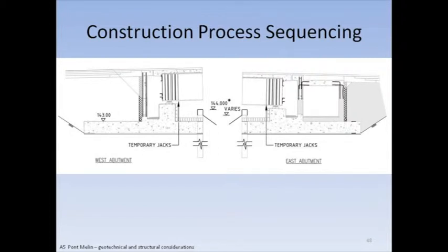The temporary jacks would mean that the level of the beams could be lifted incorrectly, but if there was settlement, they could always be trimmed into the correct place as the construction progressed, because of the risk that one corner may go down compared to another. That level could be kept.